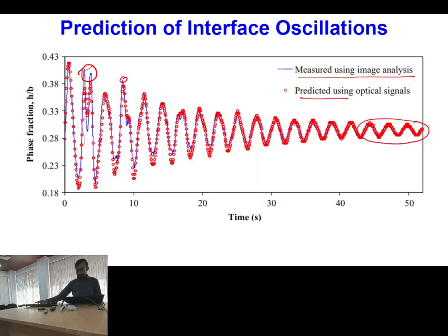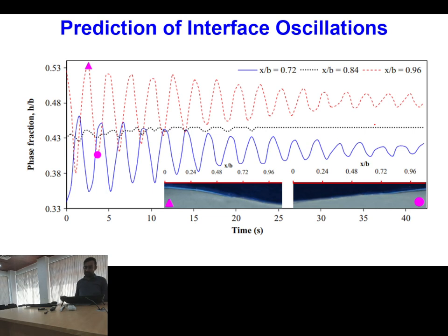So this is for a particular sensor location. Now, because you have an array of sensors, you can record the data for different sensors. So if you have oscillation about some particular point, and you take the data of one sensor above the point of symmetry and one sensor on the downstream of the point of symmetry, at almost the same locations, then both should give you the same value of the amplitude, but there should be a phase difference.